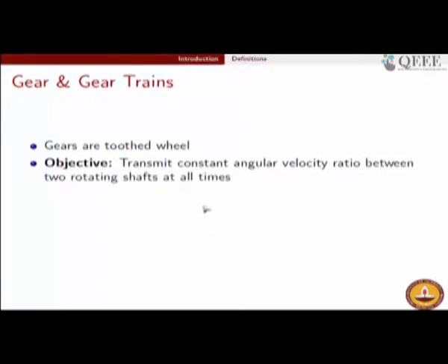You should not have a gear system where the output is a fluctuating speed, even if the engine speed is constant, because a fluctuating output speed from the transmission side can have a very detrimental effect. It will really hamper the ride quality. For example, in automobiles, it will lead to large vibration and eventual failure.